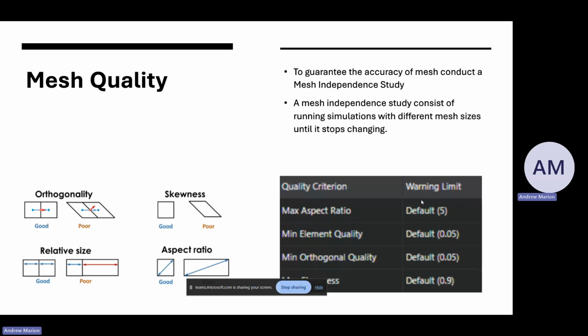I mean, I'm doing research work. For club work, you can be a little bit less accurate. And mesh independence studies take a while because you literally have to remesh it every single time, run it, and compare the results. If you're not doing a PDR or something that might call for a mesh independence study, like if they don't tell you to do one explicitly, you probably shouldn't worry about it. This wouldn't be really applicable for the club, but if you are doing this on your own and you want to get into accuracy, it's worth doing.